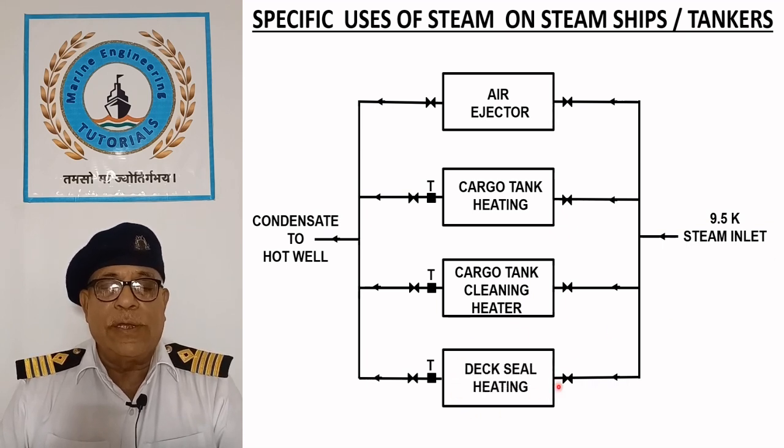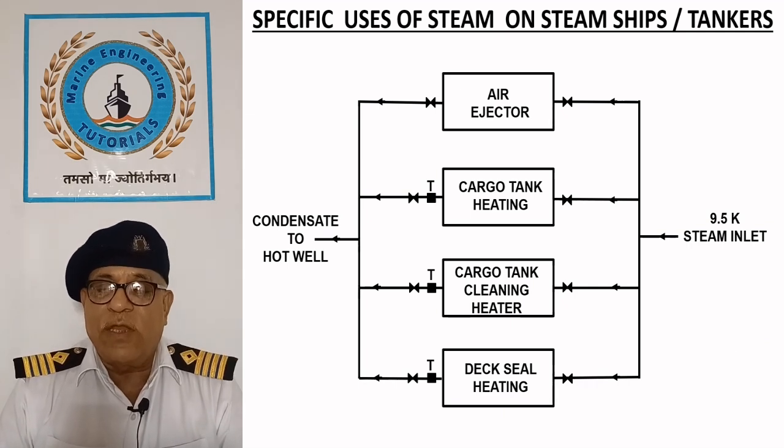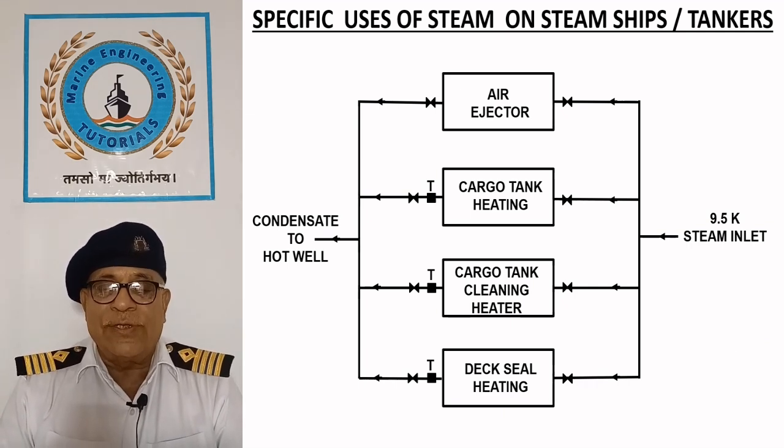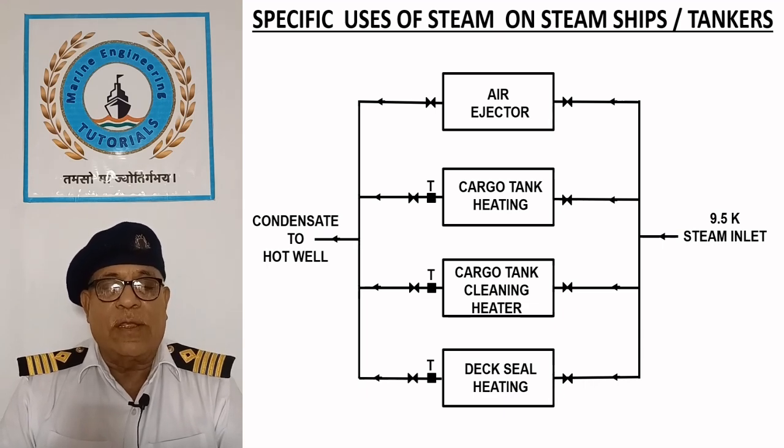Deck seal heating. The deck seal acts as a safety device of the inert gas system to prevent backflow of cargo vapors towards the boiler if the inert gas plant stops. In cold climate, the seawater used in the deck seal is heated by 9.5 bar steam to prevent freezing.